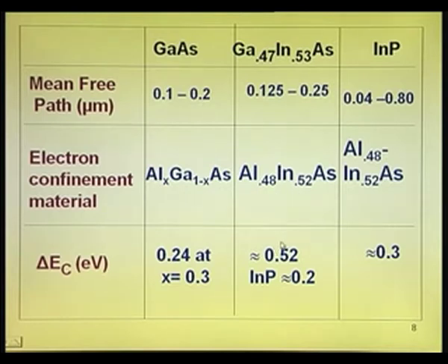Aluminum arsenide is 1.46, indium phosphide is 1.35. Even though the band gaps are the same, because the neutral level of indium phosphide is closer to the conduction band, you get the delta EC between gallium indium arsenide and indium phosphide as 0.2. Please remember that. So, when you use these formulae for finding the delta EC, do not use blindly 2/3 of Eg1 minus Eg2. Ask yourself what the neutral level is. If the neutral level location is known, you can immediately pin down how much the delta EC is, because finally, the two neutral levels align with each other. That is the key.